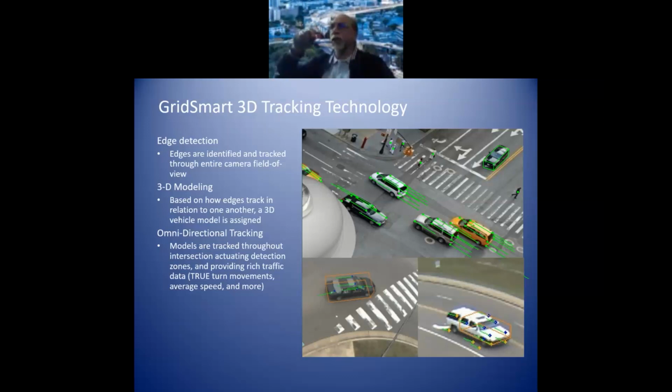So it comes into the intersection, maybe stops at the stop line because the signal is red, and then it turns left or goes straight or goes right. And the system keeps on following that till it exits the vision space. During this period, at one point of time, it will be right below the camera, and even a normal telephone camera today can actually do measurements. So there is intelligence in this that can measure the size of the vehicle, and because it is tracked from point to point, it is able to see the speed of the vehicle going through the intersection.